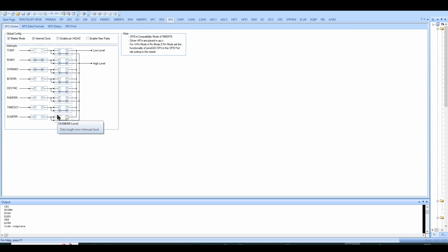Let's have a look at the options. So on the global page, we've got some settings up here for clocking, and then we've got a way of routing through these interrupts. Now actually I will turn these off. I just put those on before I made the video, but the code that I'm running, the configuration, is actually how you see it now. So none of these fuses are made, but after those fuses we then have other fuses which let us pick where those interrupts are routed.